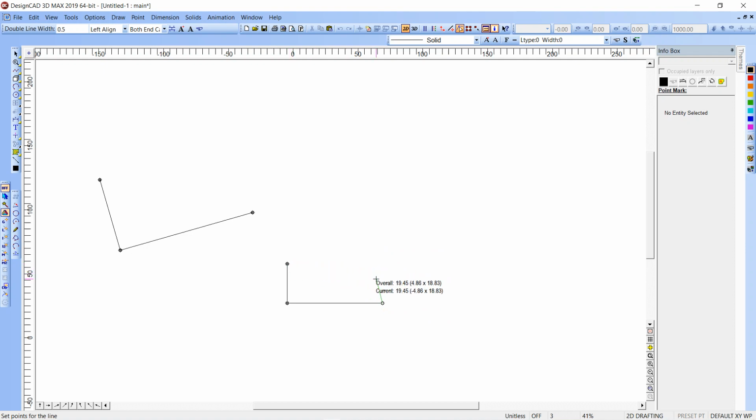So what I do is I hit JS until I want this line to be the same as this line, and then I can right click on there and it'll give me that point, enter. Same thing here, V, J, S, there, and it's giving me that line there. Lock it in. So that's how that works.